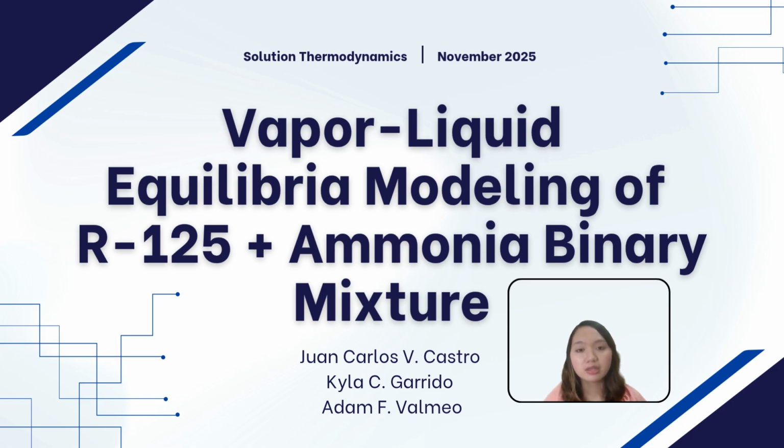Today, we will be presenting our study entitled Vapor Liquid Equilibrium Modeling of R125 and Ammonia Binary Mixture. This study focuses on developing a reliable thermodynamic model for the R125 ammonia system, which is of significant industrial importance in low GWP refrigerant blends. The system exhibits strong non-ideal interactions and double azeotropy, making accurate prediction of phase behavior challenging. By addressing these complexities, the study aims to describe thermodynamic behavior of the R125 ammonia system and its implications for industrial refrigeration applications.